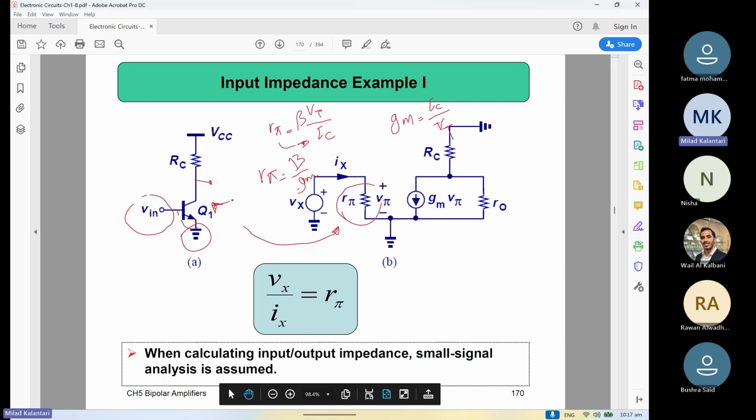So the small signal model basically starts with this r pi and the gm. All of these depend on the bias current. And then there is some big resistance of the device, r out, usually a very large resistor. And this is the load, we put it here, right?